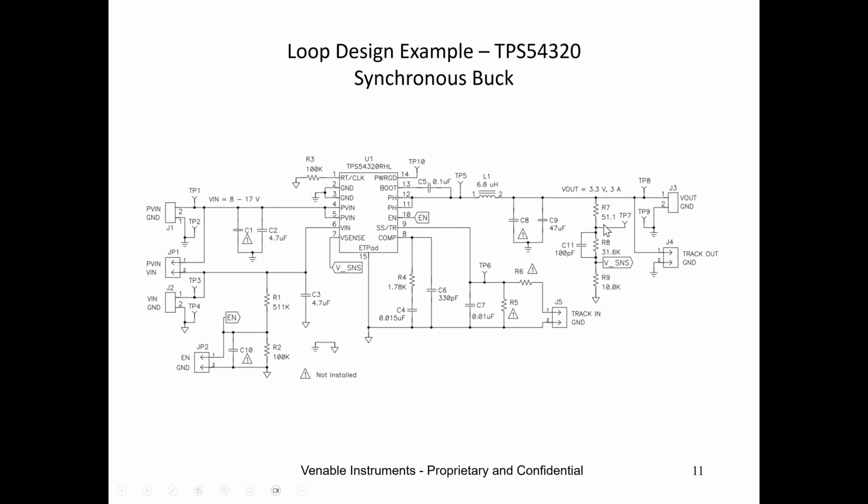You would also connect channel 1 to test point 7 and ground. And then you would connect channel 2, which would be the output of the loop, to the output of the power supply and ground. So channel 1 is on the input, right? Which feeds, this comes over here.